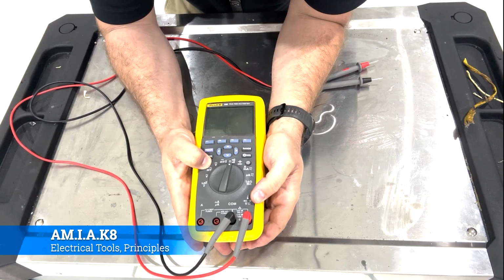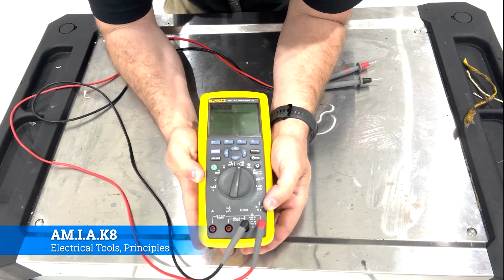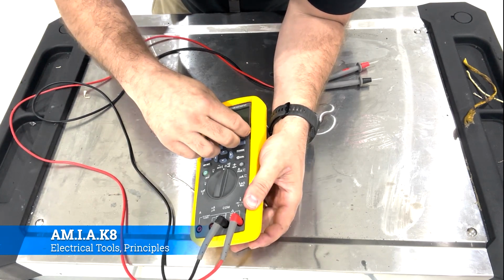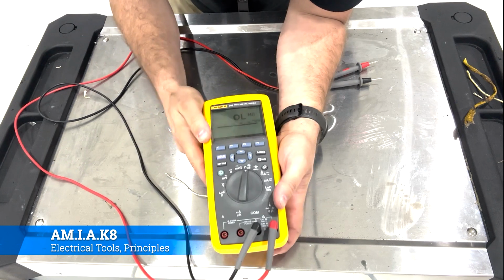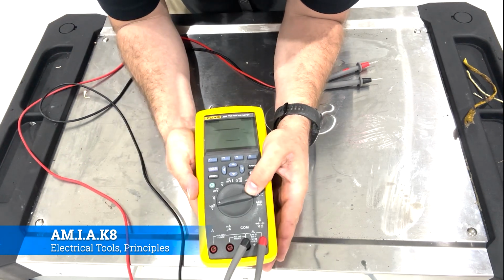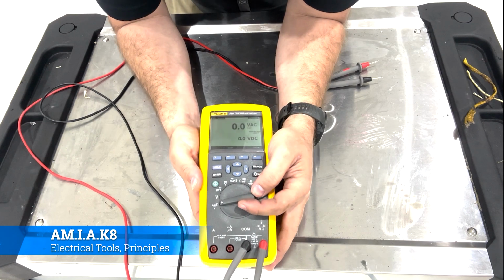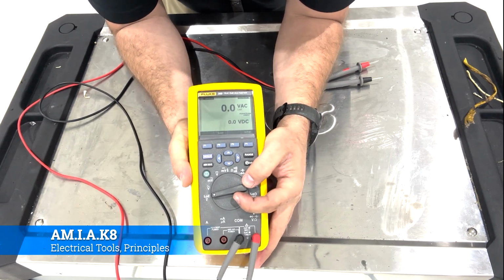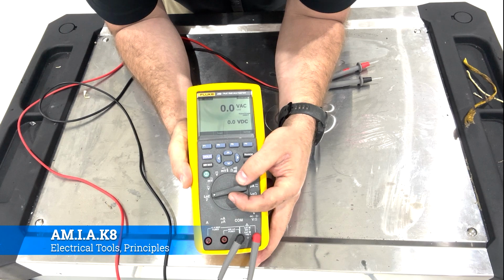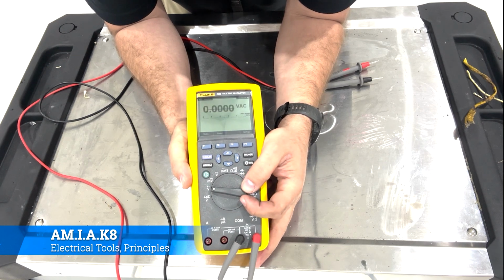Okay, first let's start by turning the multimeter on. There's a power button on this one. Some of them, however, it's integrated into the dial. Now this first setting on the far left hand side that says LoZ, that's a low input impedance to try to help detect ghost voltages. The next one up though is pretty vanilla.